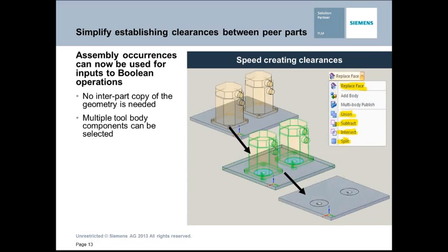With the aspect of being able to see different faces within the assembly and use those faces for modeling, we now get the ability to do Boolean operations. So, for example, in this graphic right here, we're actually doing a subtract from a tool body so that we can now get exact matches on other parts within an assembly. Very cool.